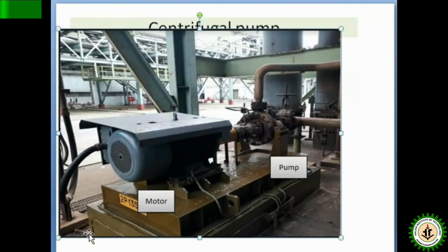First the stator will have current, then since it is a three-phase induction motor, there will be a magnetic field, and the rotor will be a conductor in the magnetic field. Then EMF will be induced, and by Lenz's law it will try to rotate to achieve the rotating speed of the magnetic field. So the rotation happens, and the shaft also rotates at the same speed, which is transmitted to the pump having the rotor, and this rotor imparts kinetic energy to the fluid. When that fluid passes through the volute, it is gradually converted into pressure energy. So that is the basic principle of a pump.